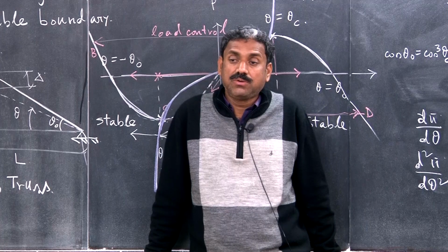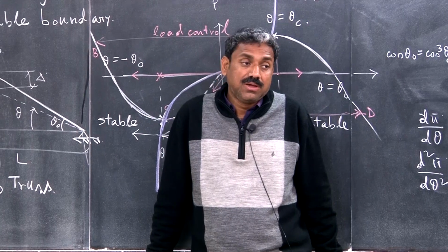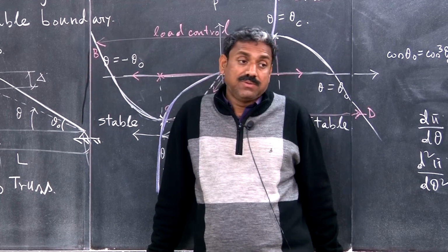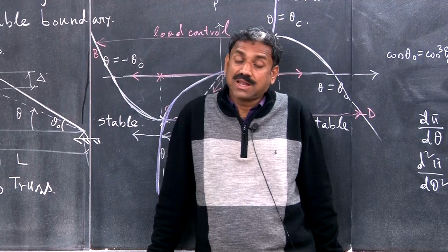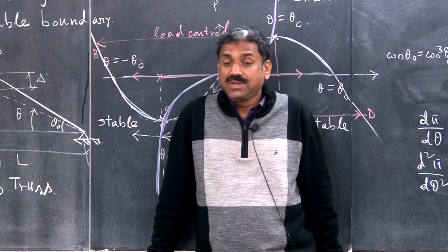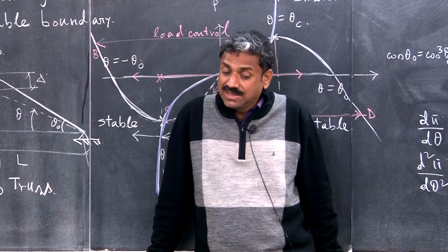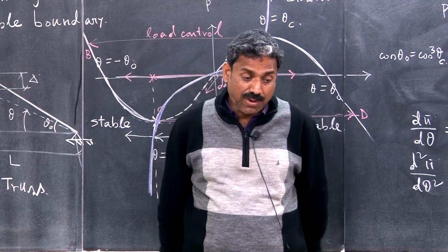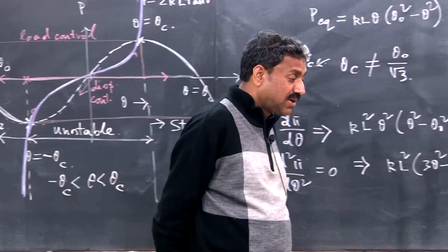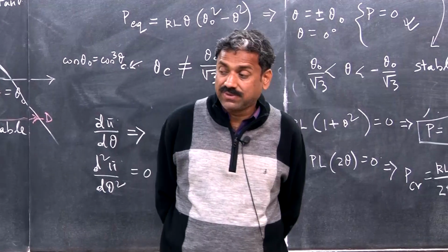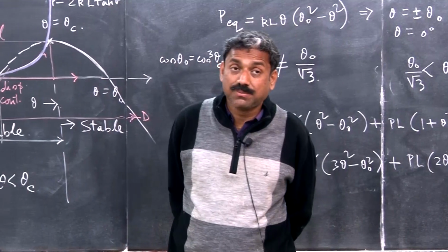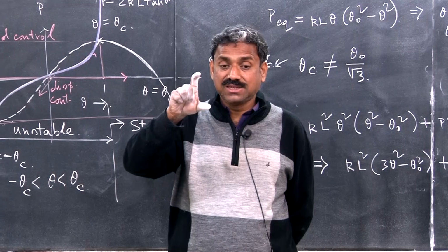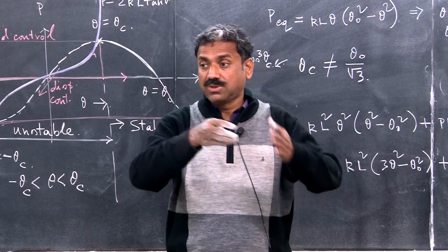In fact, a number of shell buckling problems, cylindrical shell and then spherical shell under pressure, show snap through behavior. Okay, there are other examples as well. So these kinds of systems shouldn't be linearized. In fact, this mistake has been made by many scientists in the past. A common example is the shallow arch, flat arch, an arch in which the rise is relatively small compared to the span.